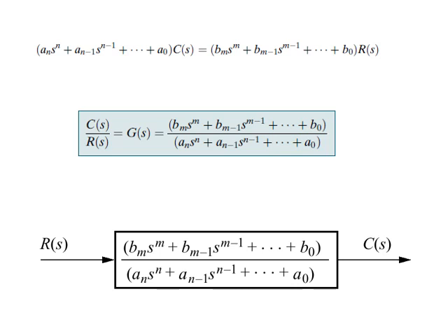After Laplace transform, our time domain equation is converted into a simple algebraic equation, and after setting initial conditions equal to 0, we can simply take variable C of s common from all the terms involving it, and similarly R of s common from all the terms involving this.